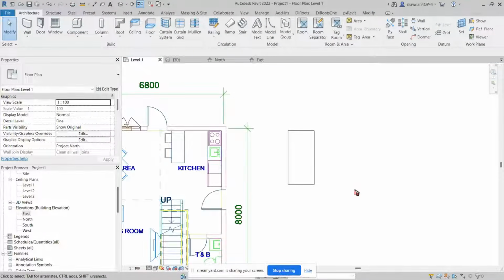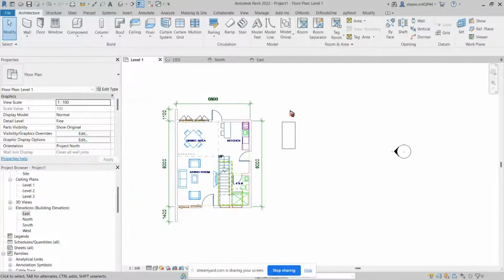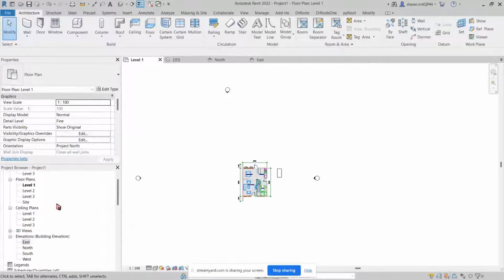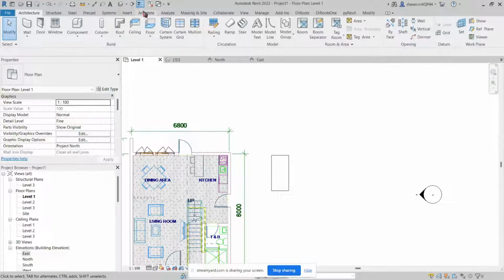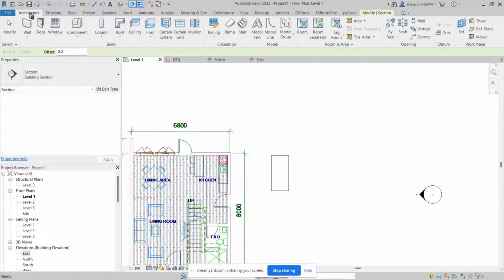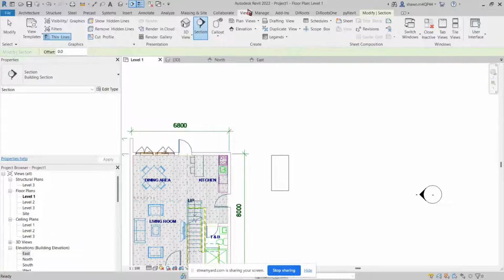And we can verify that by going to an elevation view or going into a section view. So I wanted to go to a section view, but I do not have any section icon here or even the project browser. So the solution for that is to go to the quick access toolbar. You can create a section here, or you can just go, sorry, to the view tab and select section. Then click for the first point up to the second point,